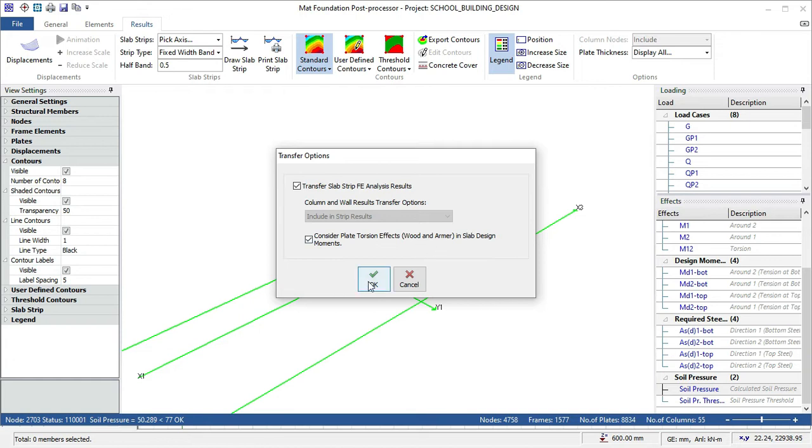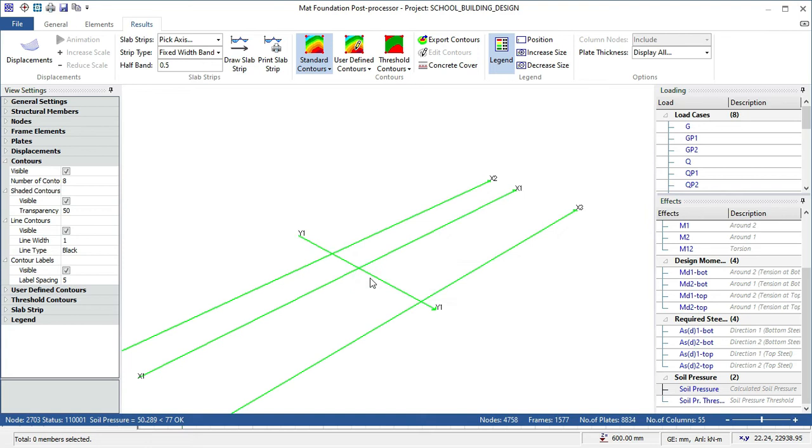Okay, so right now you can click on this place here and say okay. I'll click on okay and then wait for it to transfer all the slab strip reinforcement onto the model. Once you reach this stage, just hold on. Once this stage begins to read, you will begin to see the values here start to read. So just hold on for it to start.